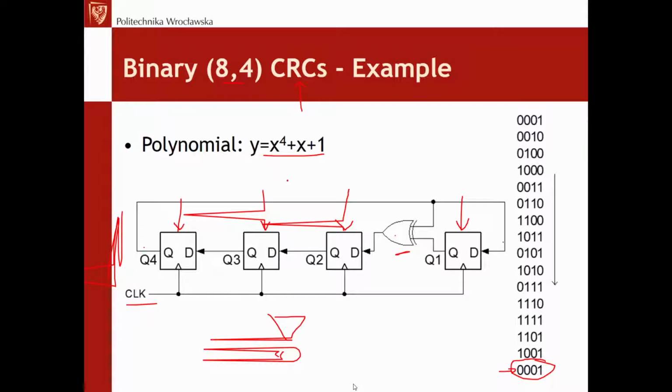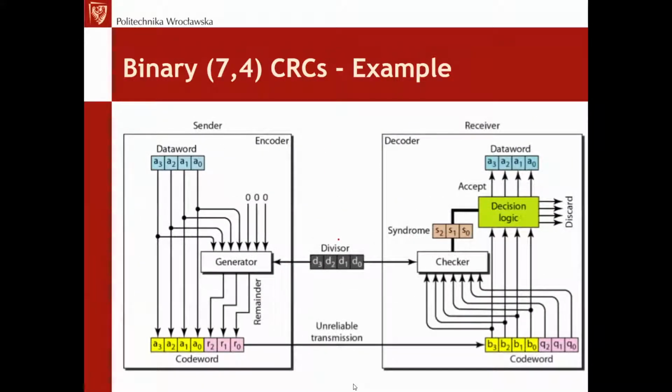Again, a small practical remark: if you want to use CRCs and not simple checksums, search for a microcontroller with a hardware CRC block inside, because that's what's available and possible today.